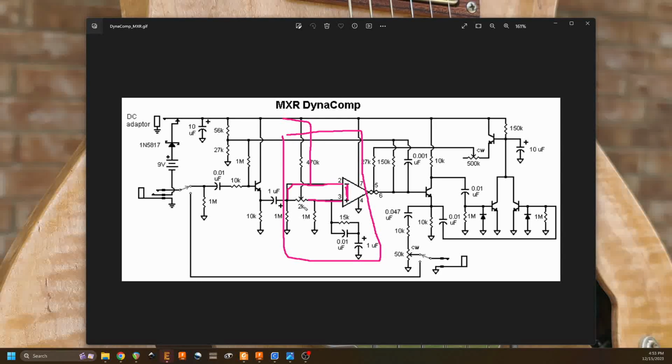I mean, if you compare the fact that we have 470K here and 2K here, it's pretty clear that really small adjustments can make a big change in really dialing in the balance on these two input terminals. Okay, so that's what this trimmer is doing.